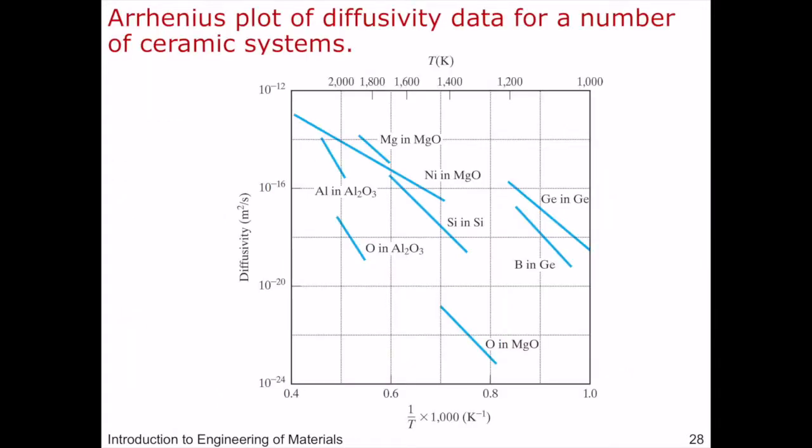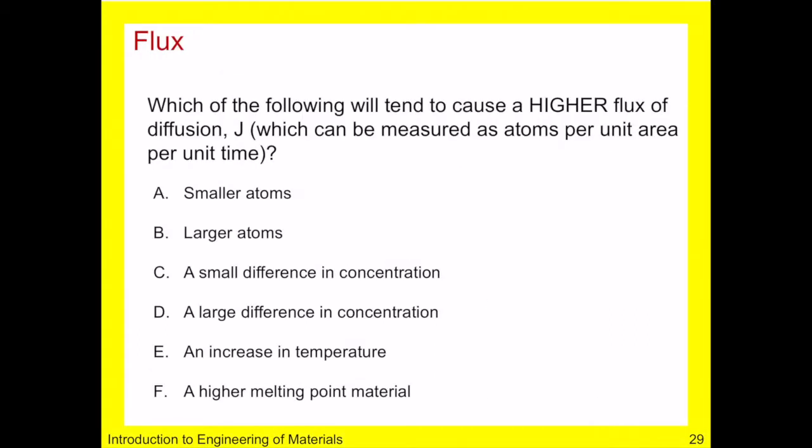And just as we've talked about diffusion coefficient D or diffusivity D for carbon in iron or iron in itself, we can also track the diffusivity values for cations and anions in ceramic systems. So here you see some examples for magnesium in magnesium oxide, as well as the oxide ions. And you could see that the diffusivity for the cation is much higher than that of the anion.